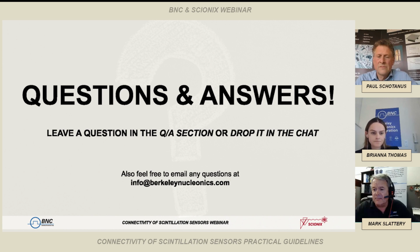Eric Lucas asks, if you have your HV supply connected directly to the PMT, does that help with noise? I'm not sure I know the further details. To my understanding, when we connect the SHV cable, for instance, to the PMT... No, if you integrate the high voltage power supply with the photomultiplier tube by bringing them close together, it does not actually improve your signal to noise ratio.